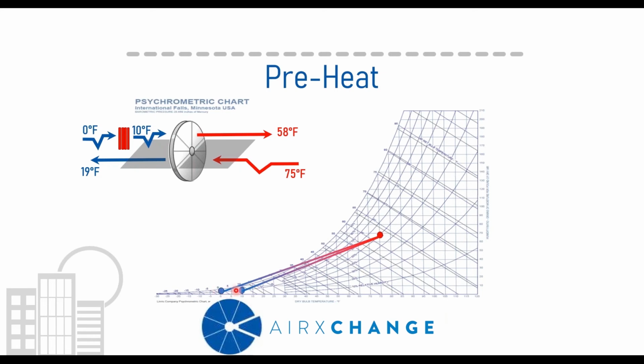And as you can see, it only takes small amounts of temperature, which could have a substantial impact on the slope of that process line. Here you can see what happens to your discharge temperatures. So adding 10 degrees doesn't really have a tremendous impact on your discharge temperature and your exhaust air temperature.